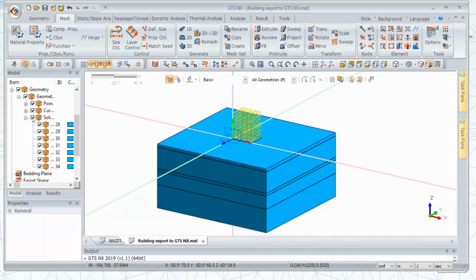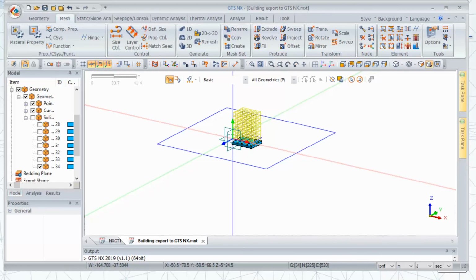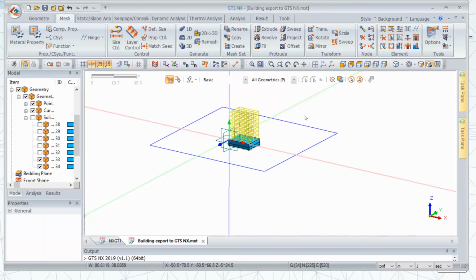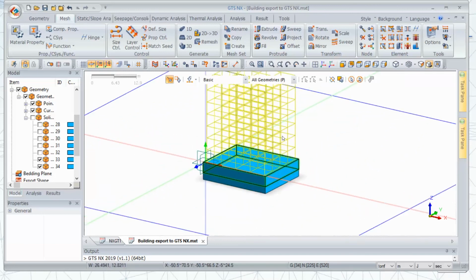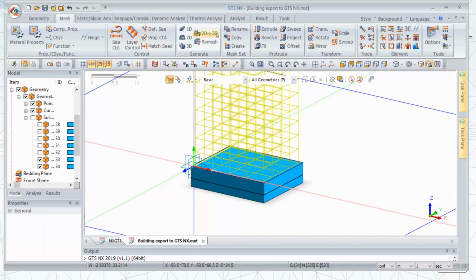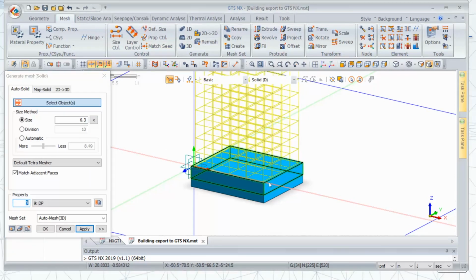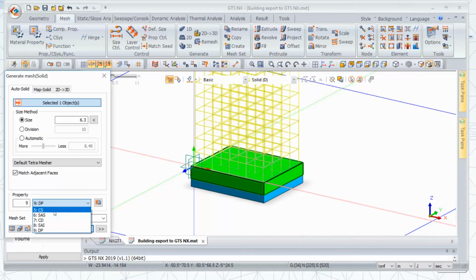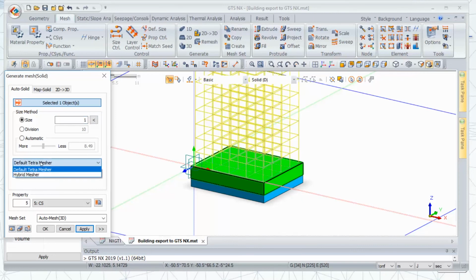We typically recommend you start meshing from the inside out. What that means is that you start with your smaller segments, and you can essentially just choose the sections of interest. You would assign the corresponding material layer to them, remember from the table, assign a value for the size of the element, and then here you can choose if it's a tetrahedral, essentially a pyramid shape, or what we call a hybrid, which is the cube shape.